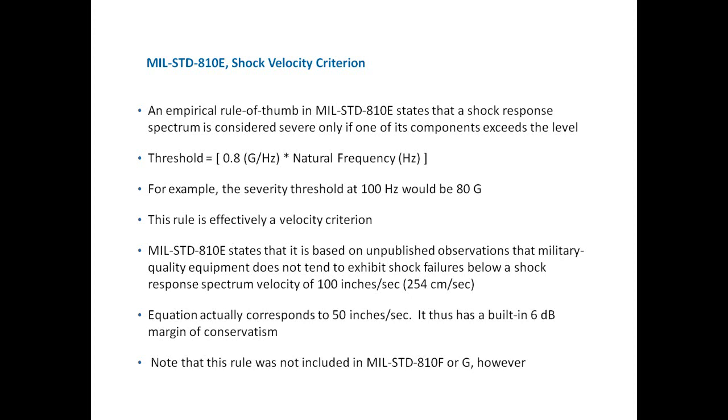But if it is military quality equipment, sometimes that formula in bullet 2, this one here, could be used to decide whether or not shock testing was even required. And another, probably a little better way than using that rule of thumb, or maybe I should say a supplementary way, is to see whether the random vibration environment is high enough to cover your SRS shock requirement. And we'll talk about how to do that in an upcoming webinar.